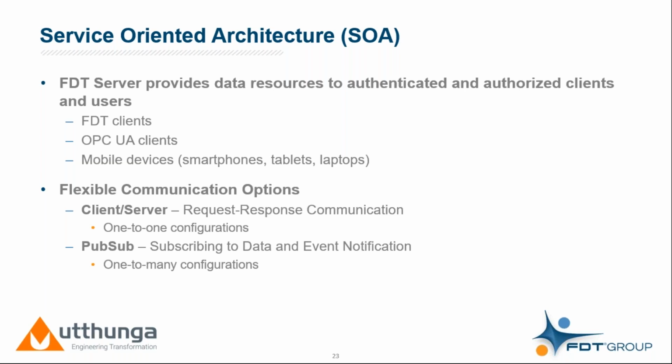And in mobile, you can also develop a mobile application, either using a mobile-enabled OPC client or a web-enabled FDT client. Since FDT supports OPC UA technology, it supports both the client-server and pub/sub mechanisms. We at Utthunga have done a prototype and research and submitted a position paper on asset health monitoring using the OPC pub/sub mechanism, and how it reduces network traffic and helps in IIoT adoption. I'll be talking about it in the next few slides.